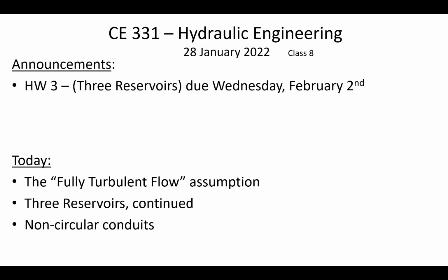It is another tool in our belt that helps us to overcome this issue we often face where we don't know the flow rate because we don't know the friction factor because we don't know the flow rate because we don't know the friction factor. You know, the chicken and the egg thing where we don't know exactly what to use as our starting F value. The fully turbulent flow assumption can be useful.